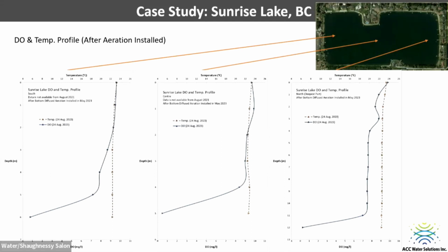If we get right down to the sediment levels, we are still seeing the sediment oxygen demand being too much for the aeration system to overcome. So we are seeing at the very, very bottom of that sediment water interface, for about 2 weeks a year, the aeration system not being able to fully deliver oxygen.